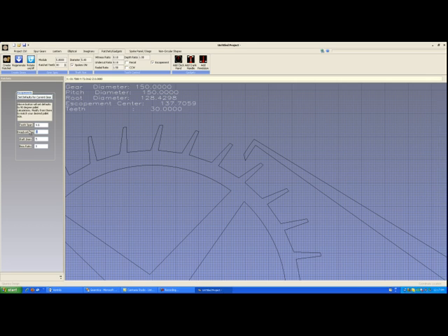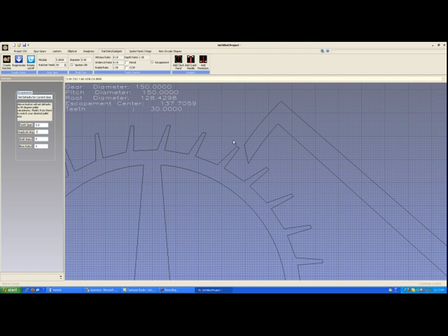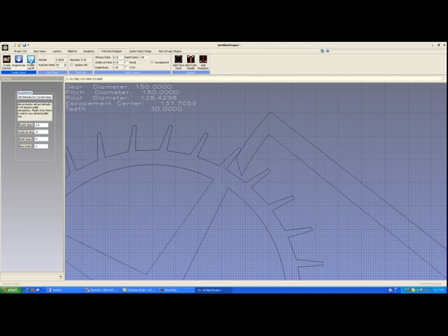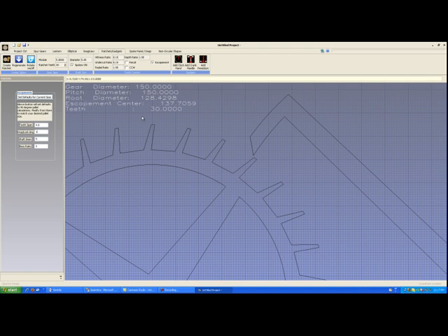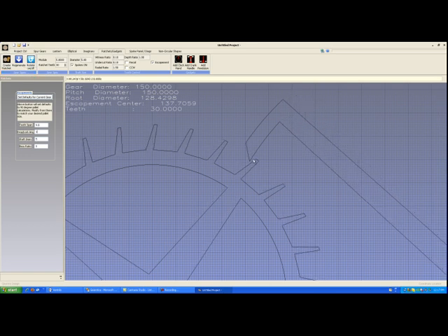So if I lower drop lock to 1 degree and regenerate, you can see if I hit rotate that when it flicks, it just flicked a very small amount. In fact, it was probably around 1 degree or less. Now watch what happens when this tooth comes back down to begin its second oscillation. We're going to come in and boom, we almost hit the tooth.